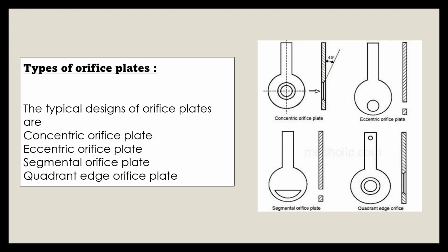Segmental orifice plate. This is used for the same type of services as the eccentric orifice plate. It has a hole which is a segment of a circle. It is used with a fluid containing more solid particles in it. They are more expensive than the eccentric orifice.